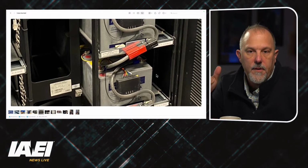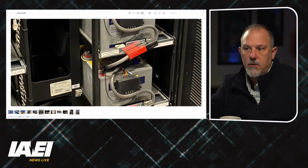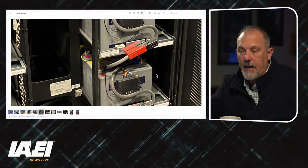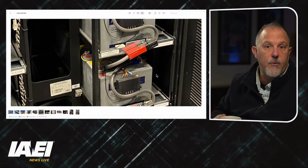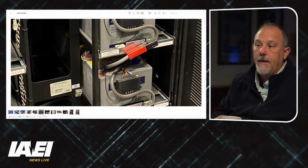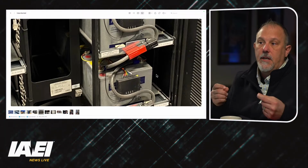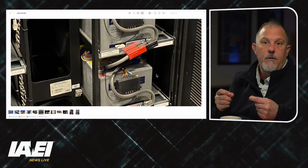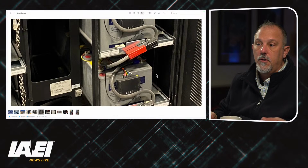It's before the overcurrent protective device. These conductors are not protected. If I have a fault of some nature on those conductors for whatever reason, I don't have a disconnect. I don't have an ability to stop that battery from providing energy to those conductors.